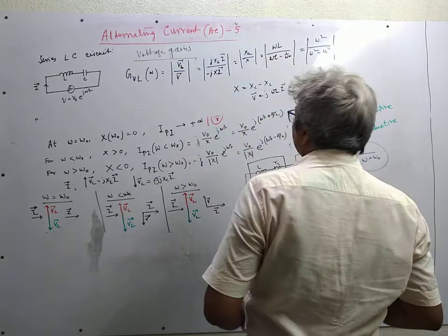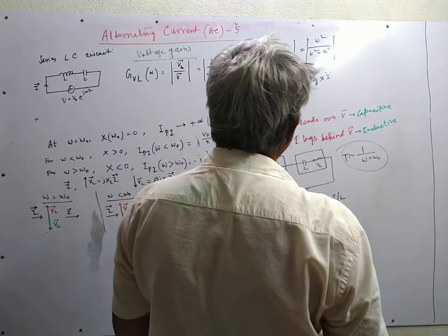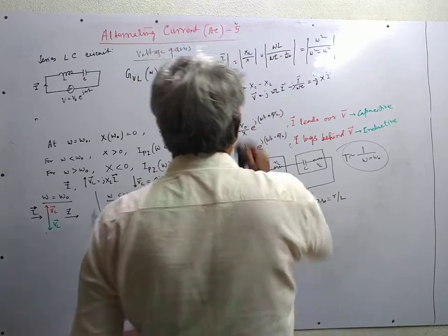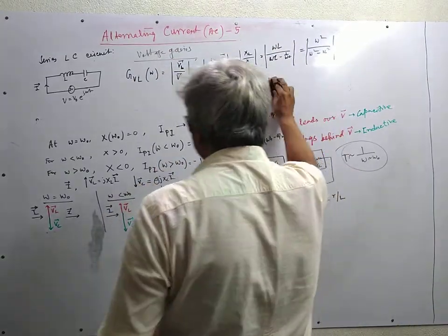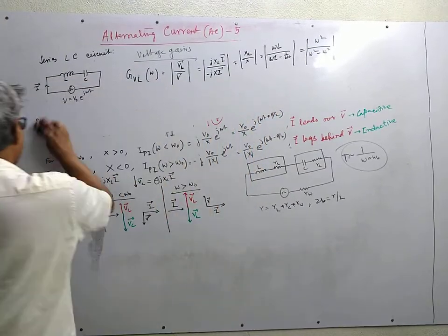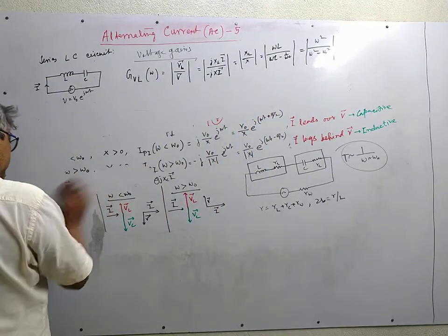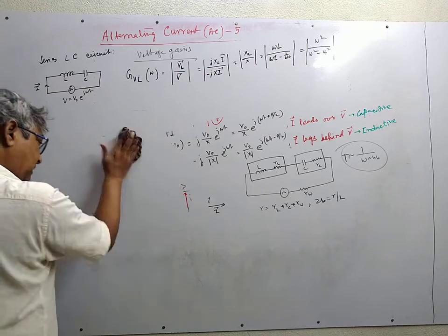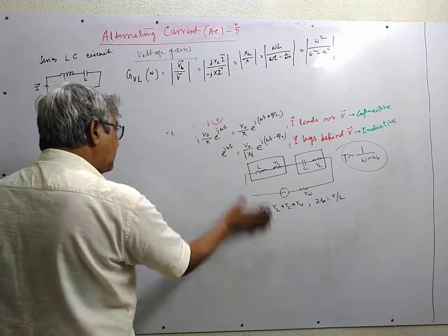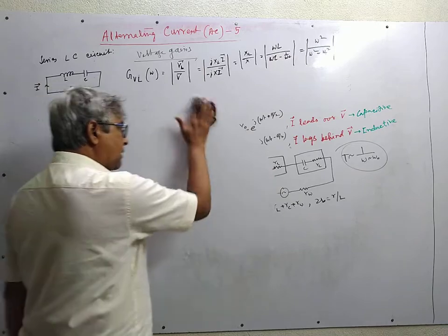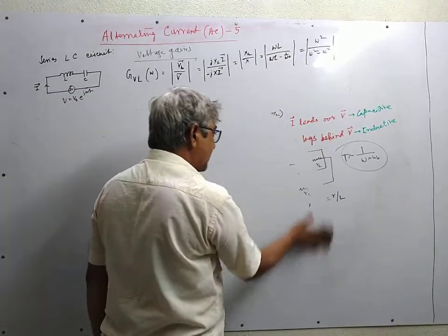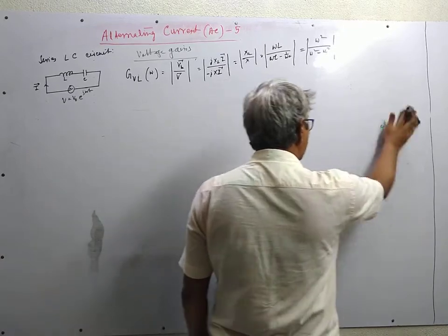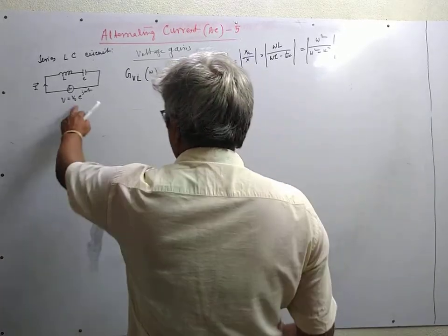So we see that voltage gain becomes infinite at omega is equal to omega 0. Note that in calculating voltage gain we have considered only the PI part, because in a real circuit the current corresponding to the CF part dies out with time, and the circuit ultimately oscillates with the frequency of the external source.